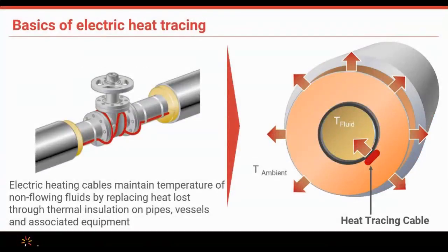So today, we're going to talk really the basics on what heat tracing is and how you guys can look at a project and be a little bit more knowledgeable on what you need to get started. So the basics is you're putting an electric cable on a pipe in this application. That pipe might be for freeze protection. That pipe also might be for flow maintenance. So depending on what you're looking at, those are the 2 things to consider.